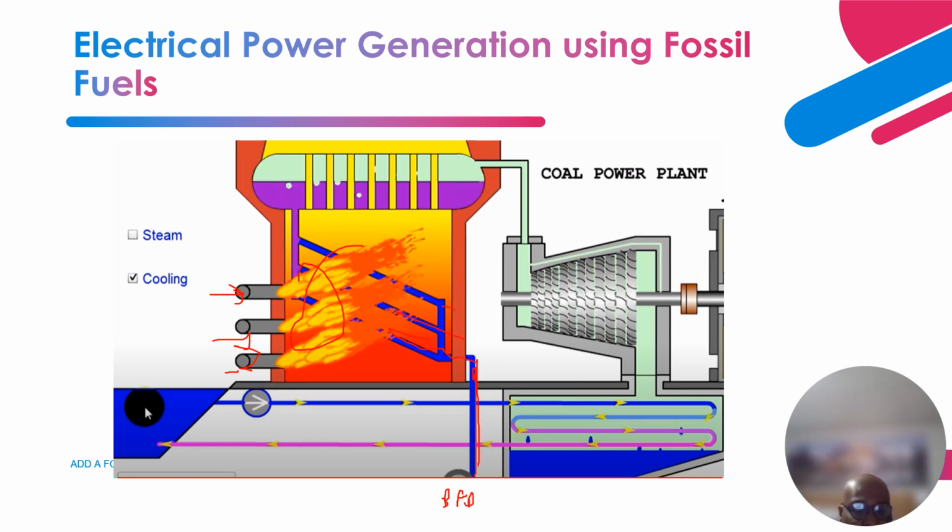As the water flows through here, it gets heated, so you have about 20% water and 80% dry steam. It rises up here and gets reheated, and goes through another superheater before it comes down as 98% dry steam and 2% water, and goes through the turbine.